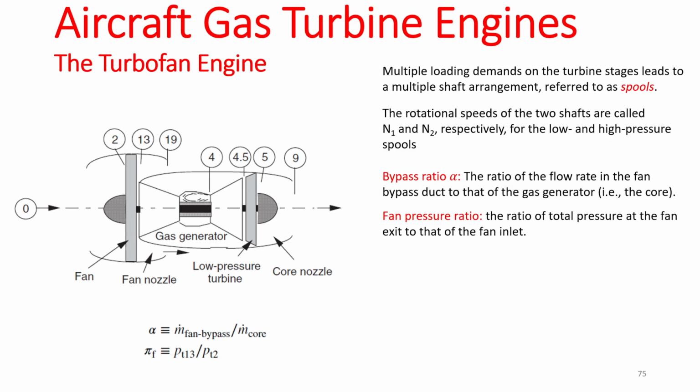This specific type of turbofan engine is called the separate exhaust turbofan engine, which is very self-explanatory, right? Essentially, it means that the exhaust of the turbojet engine, or the core of the engine, is going to be separated from the exhaust of the fan. This separate exhaust makes the calculations and the analysis much simpler, but it doesn't mean that we don't have any other type of turbofans.